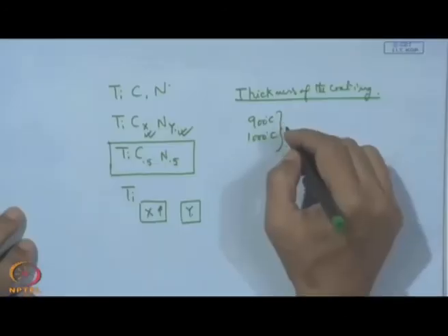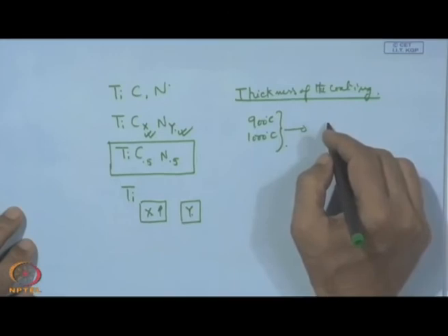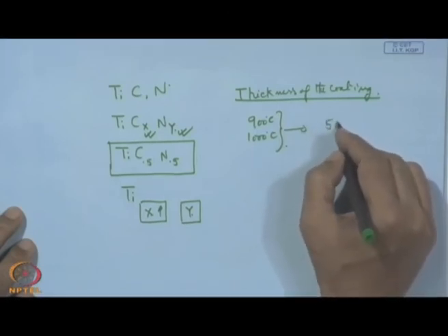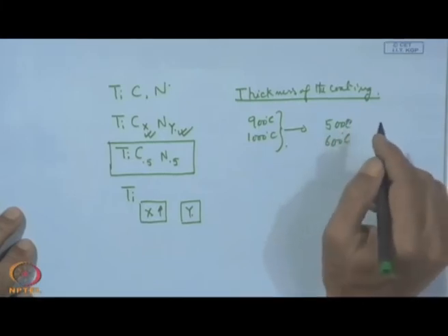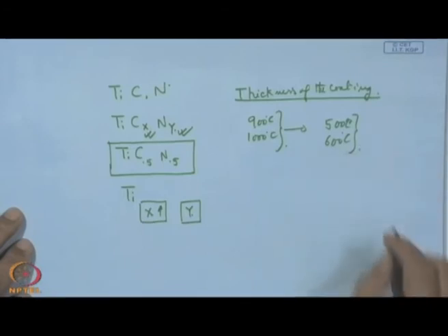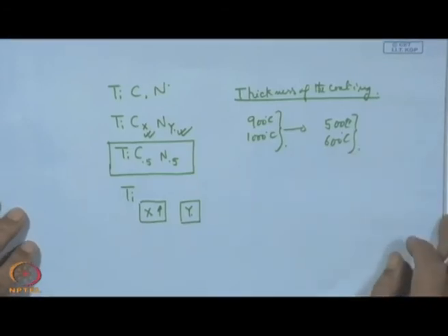It is not the cohesion, not the density of the coating, but just the separation at the interface because of this high stress build up, and that is why we have to keep it within that range. But here the situation is a little different, because this deposition can now be conducted in the range of 500 to 600 degrees centigrade. So, this gives us a clear edge, a leverage of increasing the coating thickness.